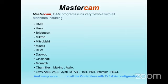Let's say I have a Haas VF8 machine which has a FANUC controller. Then you will have to convert that program according to your machine details, which will be provided by Mastercam. So there is a process called post processing, or developing post processors, which will be enabled by the machine manufacturer as well as Mastercam.